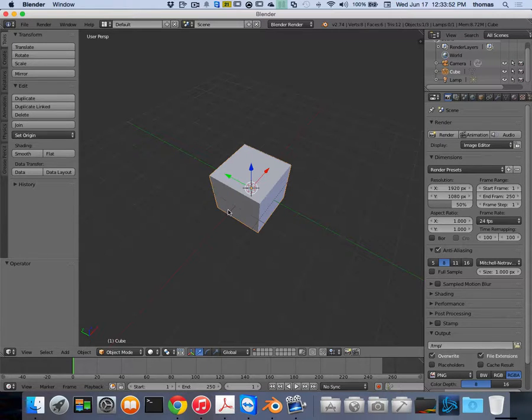Whatever the material is that's on there, you can use different shading. So these are modifiers. You can start modifying your faces, mostly faces, edges, and vertices from a shading perspective, according to the material type. It's almost like I produce a layer, and now that I've coated the face with material, I can do stuff to it. I can add shading, I can add color, I can add specularity, I can add all kinds of other stuff. So that's the material.